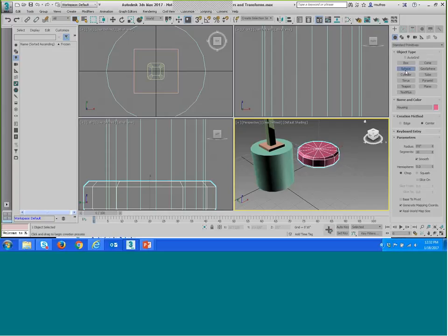And then enter a radius. We'll click and draw it in the perspective view anywhere, and then I will just modify its size and also its shape. So what I can do is give it a radius of 1 inch exact, and then leave the segments for the time being as 10.